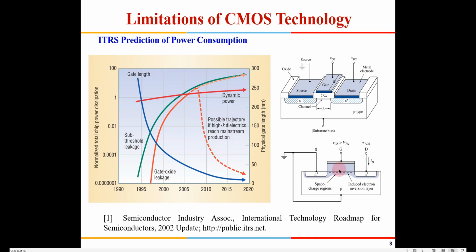So the electrical property of 1 nanometer thick silicon dioxide will be the same as that of 4 nanometer thick HfO2. That is the reason why, by migrating from silicon dioxide to HfO2 and using higher thickness gate oxides while maintaining the electrical characteristics, because HfO2 has a higher K dielectric, we are able to control the gate leakage current. That's why this line has actually not gone up and is under control as of now.